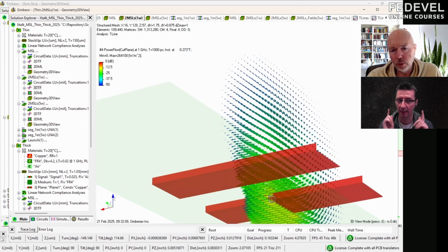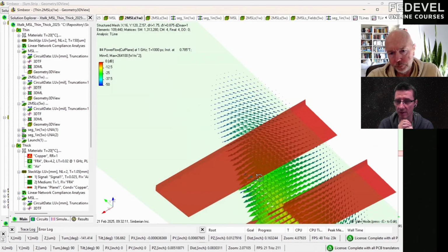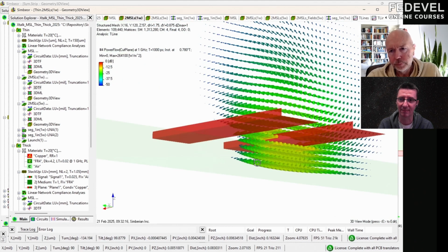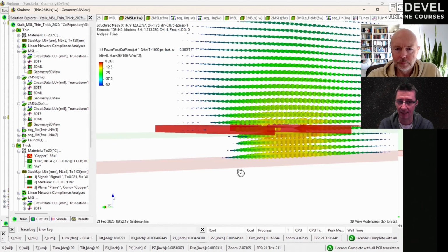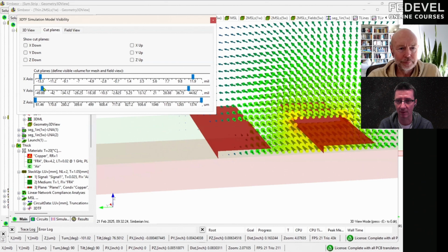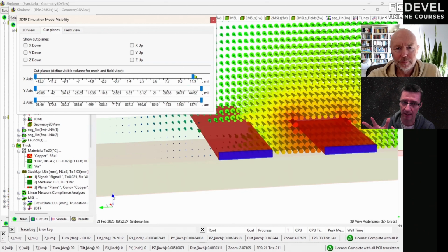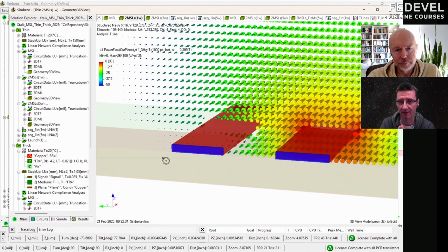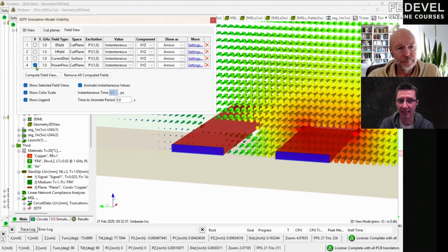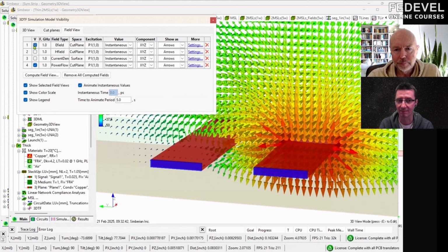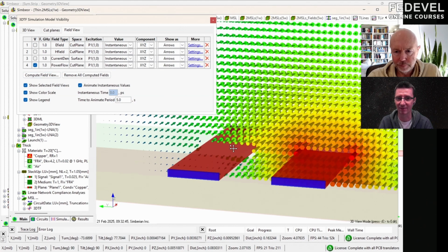So I would like to highlight what you just said, because everyone who starts with electronics in elementary school is taught that currents are flowing through the tracks, and that voltages and currents are what is important. But what we see in this simulation are the fields around the tracks, and that's where the energy is traveling. That's why the environment around the tracks gets affected by the signals, because the signal travels also around the tracks.